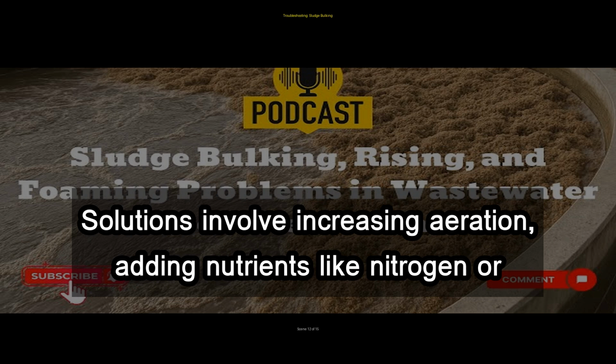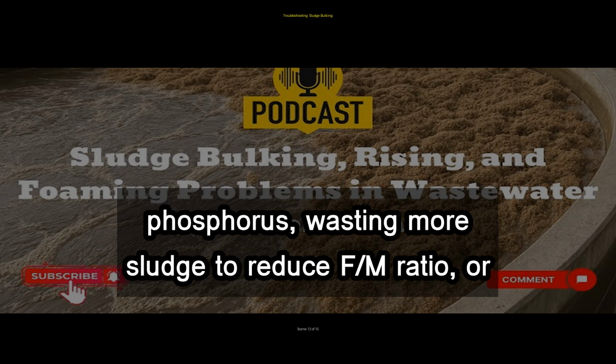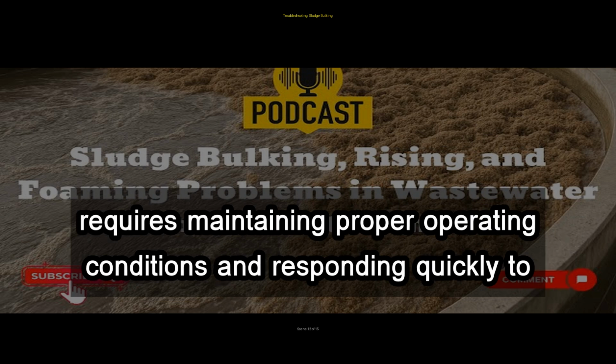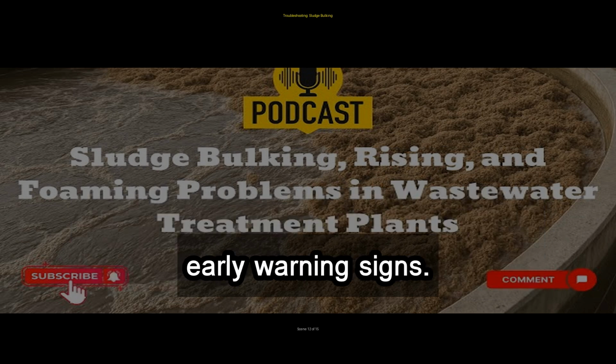Solutions involve increasing aeration, adding nutrients like nitrogen or phosphorus, wasting more sludge to reduce FM ratio, or using chlorine to selectively kill filamentous organisms. Preventing bulking requires maintaining proper operating conditions and responding quickly to early warning signs.